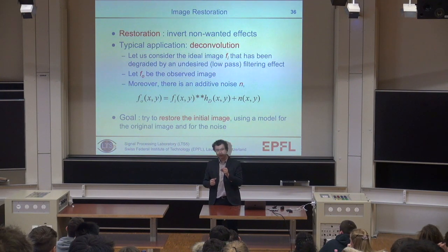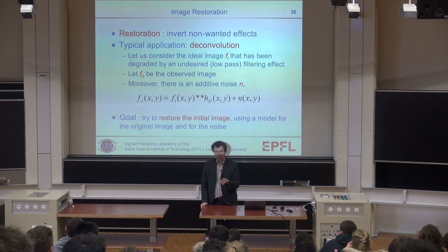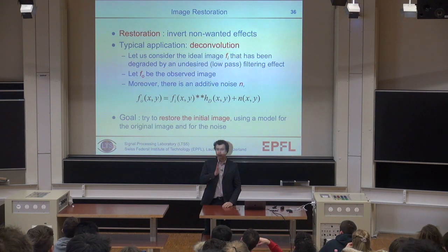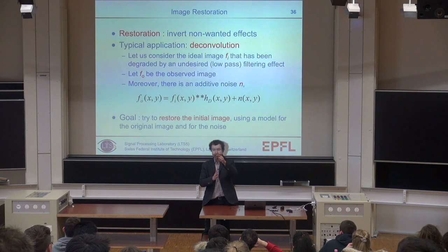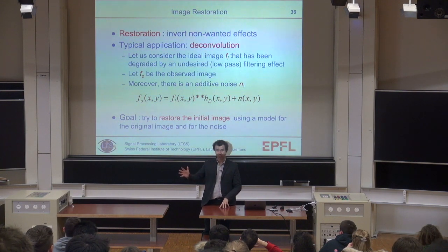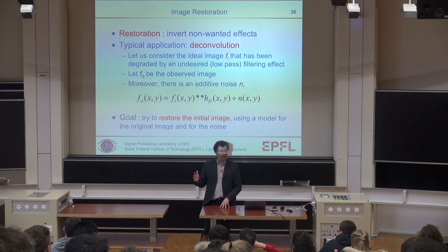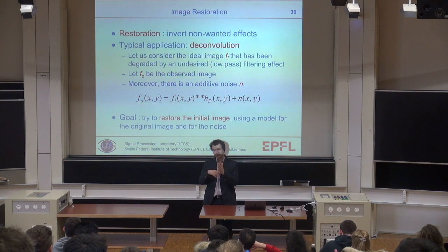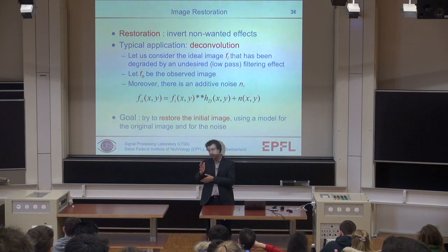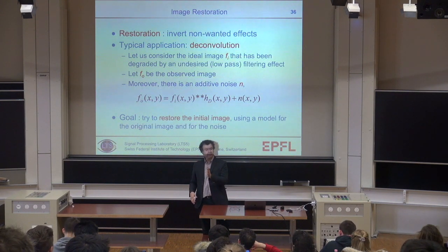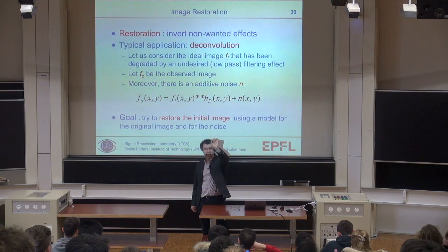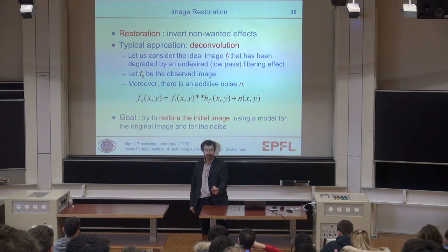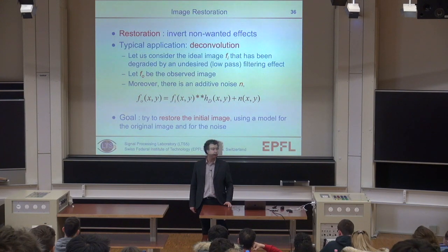I would like to have a filter that will adapt to the content of the image and to the statistics of the noise, such that the frequency response of the filter will be decided by whether I have more image than noise at that frequency, at each of the frequencies. Do you have that intuition? Do you see the rationale of that? So we want to really design this optimal filter, frequency by frequency, looking at each frequency of the spectrum and deciding for that frequency what should be the value of the filter, whether it should be amplifying, so a high value, or whether it should be a cutting filter at that frequency that would basically put the signal down to 0 at that frequency.